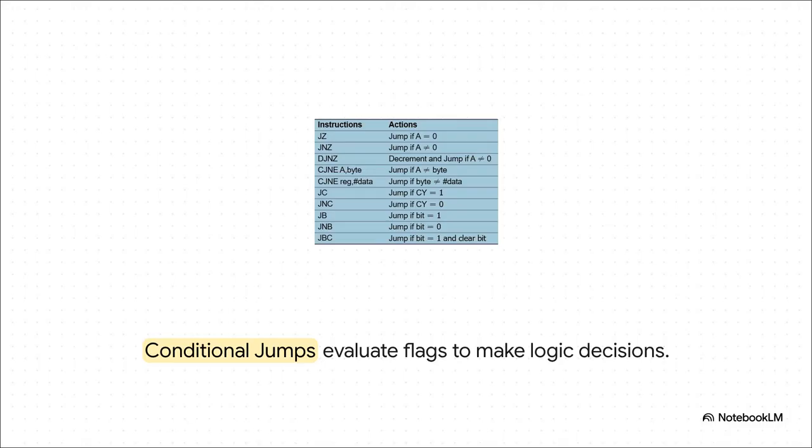And check out how conditional jump instructions let the 8051 make smart, on-the-fly decisions based directly on those PSW flags we talked about earlier. Take DJNZ, decrement and jump if not 0. That right there is the absolute powerhouse instruction for running our loops.